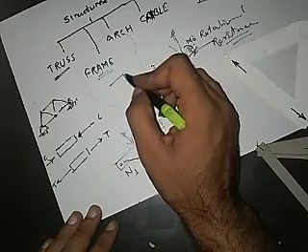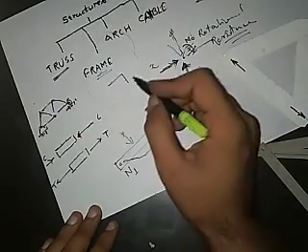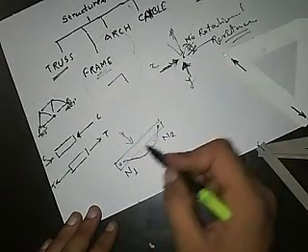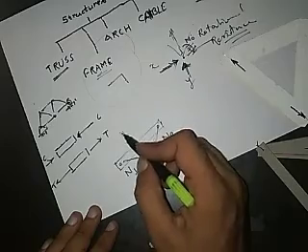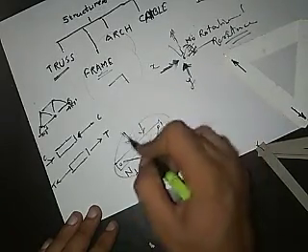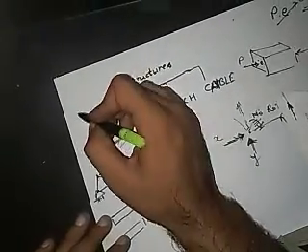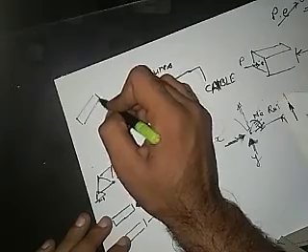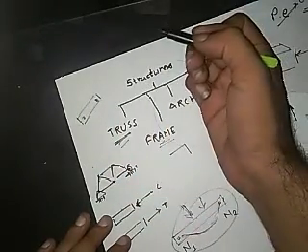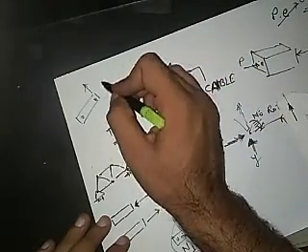Okay, it offers resistance, but a pin joint does not. So when we discuss frame structures, we can apply some bending load in between these two nodes. But in the discussion of trusses, the loads will always be transferred or applied through the nodes.